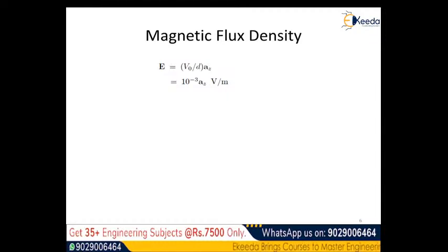Now here we go, as we have the electric field intensity, now we have to make a computation of the cross sectional current density, that we usually denote by the letter capital J, which is just the multiplication of sigma, the conductivity provided in the problem statement, and the electric field intensity. So here we represent J is equal to sigma E. See, J is equal to sigma E is also sometimes considered to be the Ohm's law in the wireless medium here. So E is showing us the electric field intensity measured in terms of volts per meter.